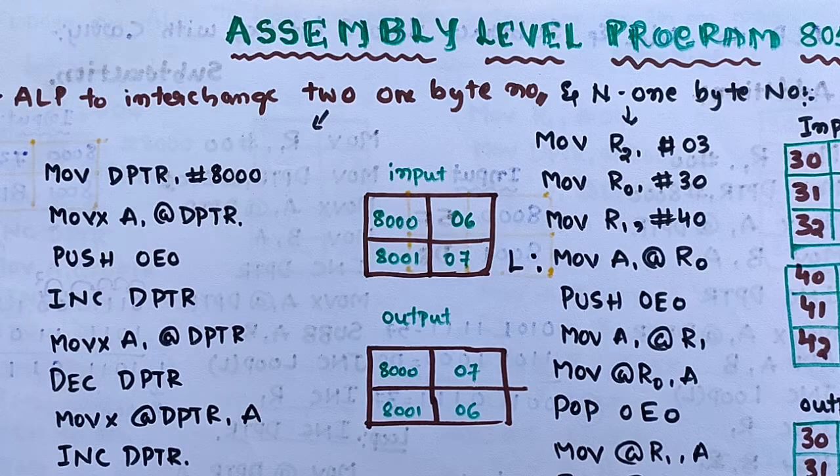In order to program any microprocessor or any processor, we need to study the different instruction sets, because each processor has a different instruction set. There are three ways to program any processor: machine level programming, assembly level programming, and programming in C. But in this lecture we are discussing only assembly level programming, which makes it mandatory to understand each and every instruction in 8051. If you are able to understand all five types of instruction set, then only can we write the program in assembly level.